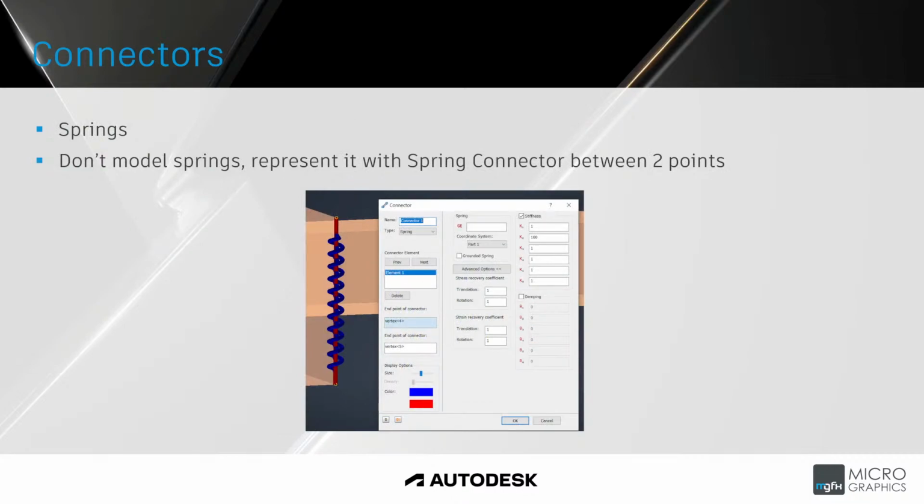Springs as well. So how do we model a spring? You don't want to actually model a spring, and also it'll be a bit difficult because it won't accurately show the forces. So what we can do is put a spring connector in between your two different points, and then put in the appropriate stiffness for it.